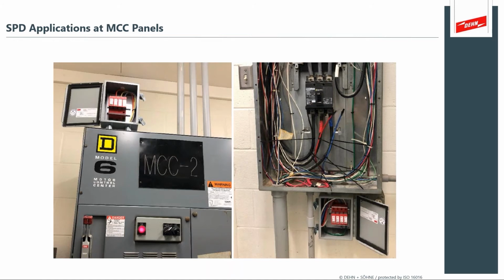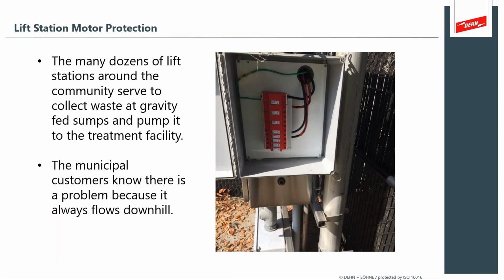So here we have a few photographs showing the SPD applications at the motor control panels inside of the water process facility, where the SPD is directly on the main switchboards to provide protection for the loads on those switchboards. And here's the surge protection devices installed downstream from the main MCC directly at the pumps.